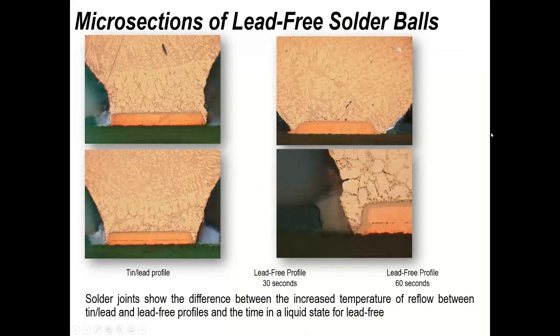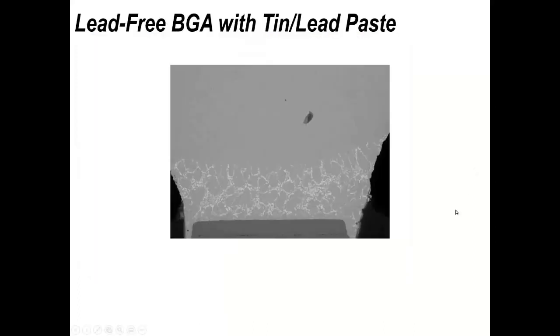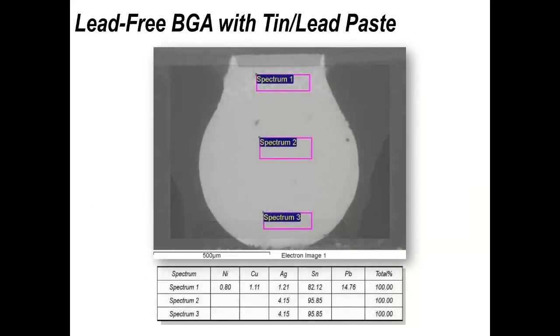And in addition with microsectioning, of course, you can do other things. This is an example where I'm looking at a microsection of different soldering temperatures, different times with different materials, and looking at the characteristics. I'm then taking that sample, and then I can do analysis on that.